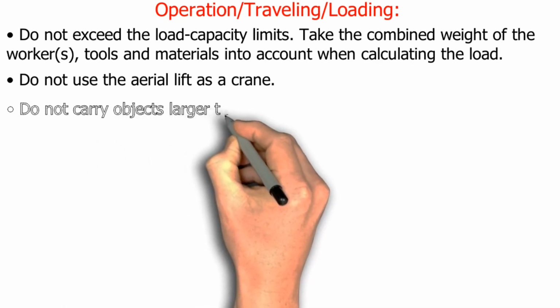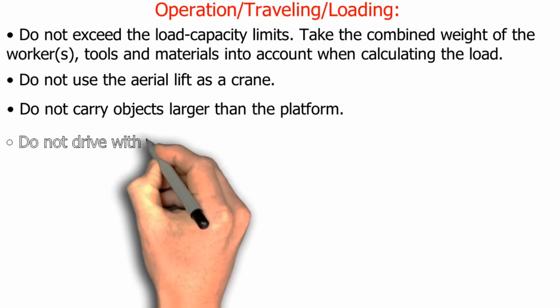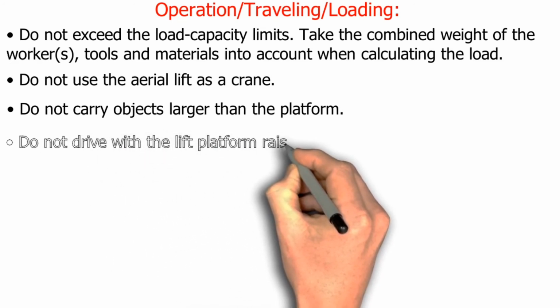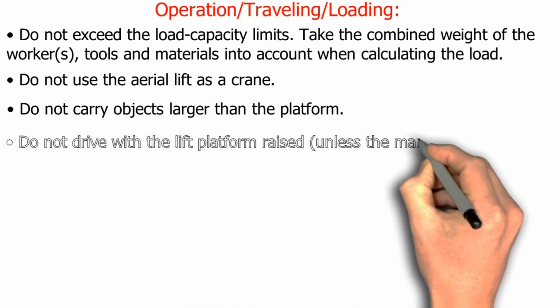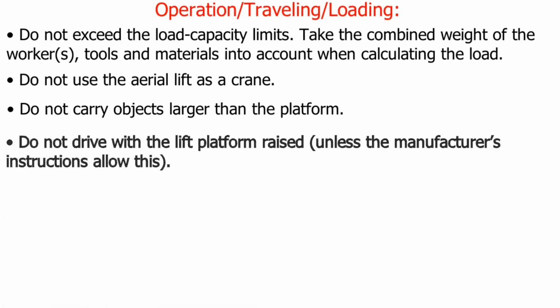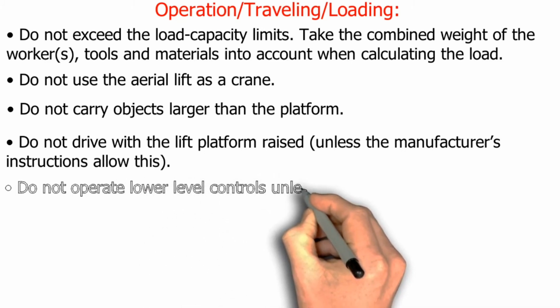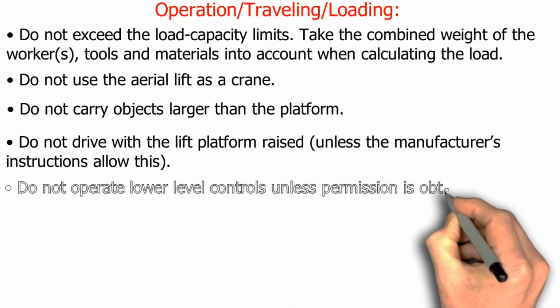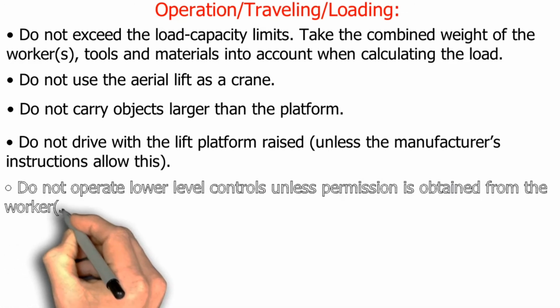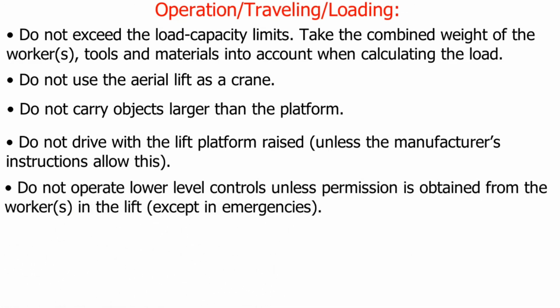Do not carry objects larger than the platform. Do not drive with the lift platform raised, unless the manufacturer's instructions allow this. Do not operate lower-level controls unless permission is obtained from the workers in the lift, except in emergencies.